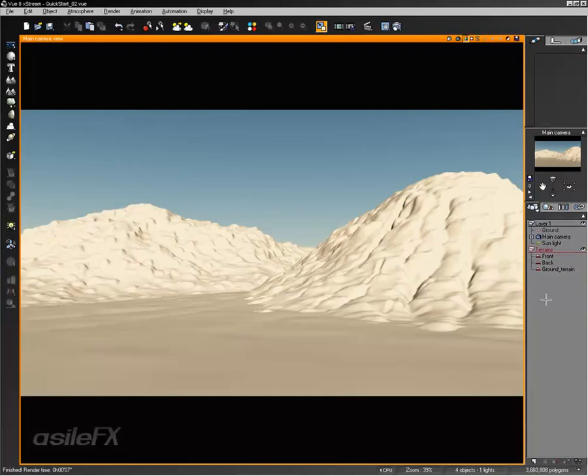So looking at a render, it's very basic. And all I did was just left click on this camera to render what I have set to render the view. Now the difference between rendering to the view this way and also using the quick render option is that it will not display the framing strips within the preview render. And I do want to see the aspect ratio and what's going to be cut out and what's actually in the frame. So it's very basic.